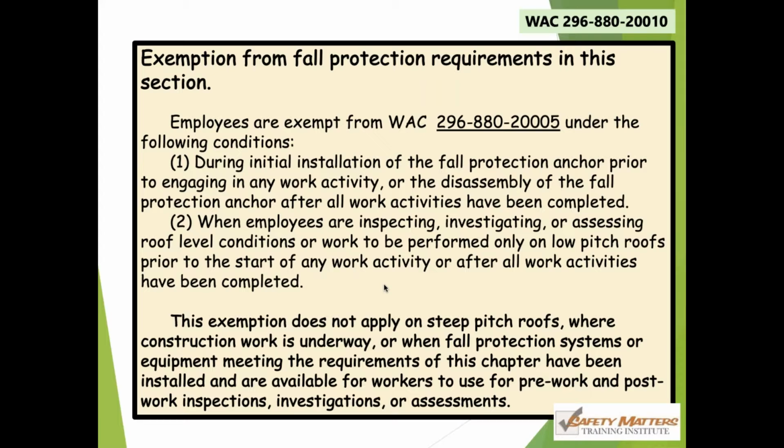I have an exemption. Second one, when employees are inspecting, investigating, or assessing roof level conditions or work to be performed only on low-pitch roofs prior to the start of any activity or after all work activity has been completed. If you look down at the bottom, though, it says this exemption does not apply on steep pitch roofs. If we're on a steep pitch roof, 4 feet, regardless, we have to protect these people.